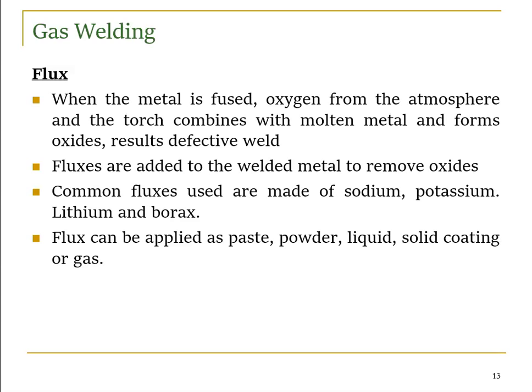Flux is one component used in the welding process. When the metal is fused, or if you raise the temperature of the workpiece material, the oxygen from the atmosphere and the torch combines with the molten metal and forms oxides, resulting in a defective weld. After welding, the joints are at high temperature, so they will react with the atmosphere.